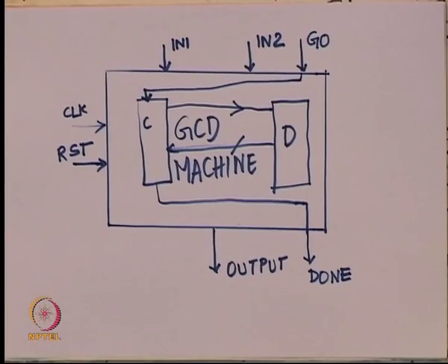This brings me to the end of this video lecture. What we saw is that we took the basic design of the chip and broke it down into two parts, the controller and the data path, and this is what you will do for most algorithms. If you are given an algorithm to implement, you figure out the data path that is required, what the control is supposed to be, and what kind of interactions should happen between the controller and the data path. Once you put these two together, the controller may take more external inputs and give external outputs, and the whole thing becomes a chip. This is what we are going to do in the next few videos. I hope so far this is clear.